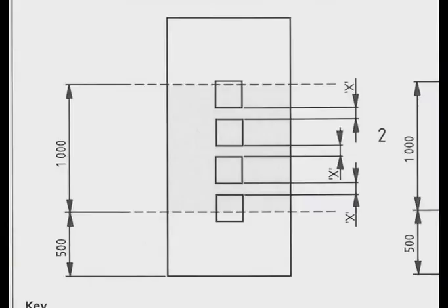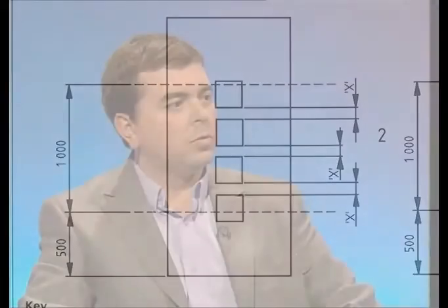So is that more or less right then, Fausto? It is. There was a lot of criticism within the industry that the previous standard actually meant that door designs were very institutionalized, with a very long, thin vision panel. So that was recognized, and the new standard allows for obstructions of about 350 millimetres. But it means that they can be added up within the design of the door rather than... It means designers and architects have got a lot of freedom. More freedom to make an aesthetic-looking door.